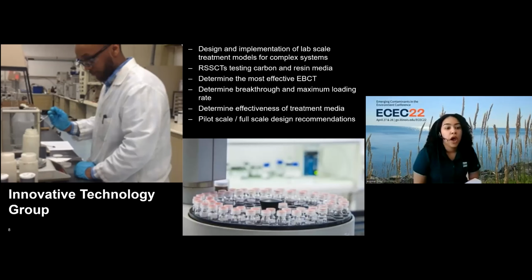Okay, so our treatability testing occurred internally with our innovative technology group that we have with GHD. And what they did was perform small scale column tests that were specifically testing manufacturer resin and carbon. So we had 2 resins that were being tested and 1 carbon that was being tested.